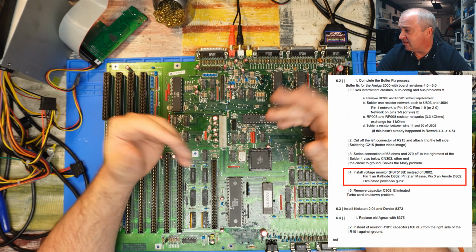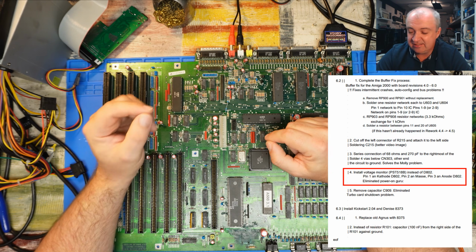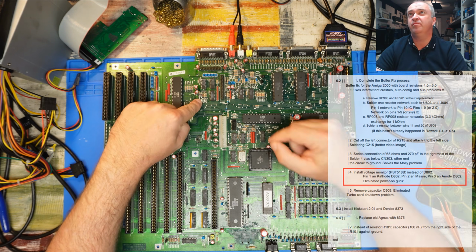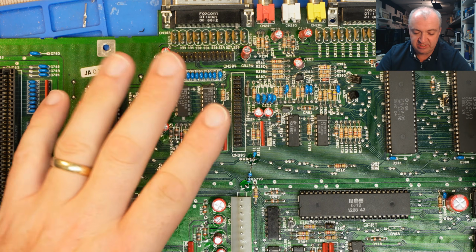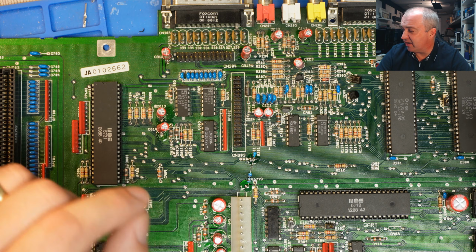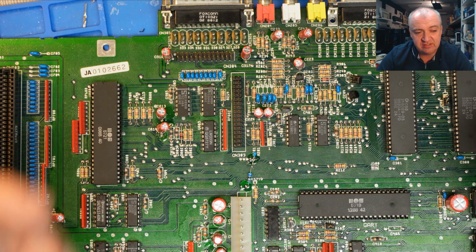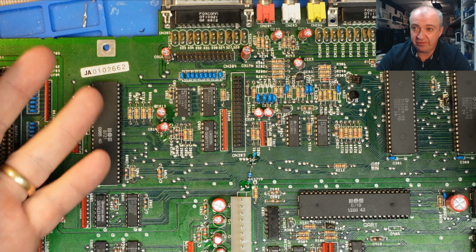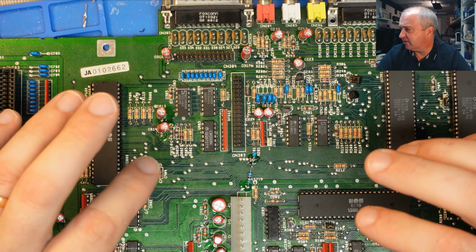So next thing we need to do then, item 4, install the voltage monitor PST518B instead of diode 802. Well, that is diode 802. That forms part of the power good circuit for this board, basically holding the machine in reset until 5 volt comes up stable, then it releases it. Supposedly by doing this mod it eliminates a power on Guru. Now I know certainly in the likes of an A500, if you toggle its power quickly it will throw a Guru. So I'm assuming it's fixing that sort of similar problem with this 2000.